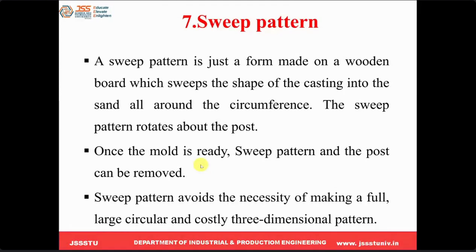Basically this sweep pattern is used when you produce circular objects. Then it uses a pattern called a sweep pattern. Basically it is just made up of a wooden board which sweeps the shape of the casting into the sand all around the circumference.